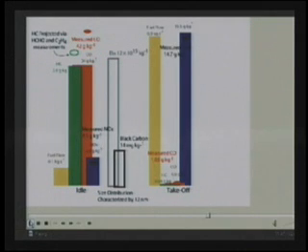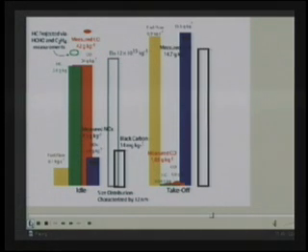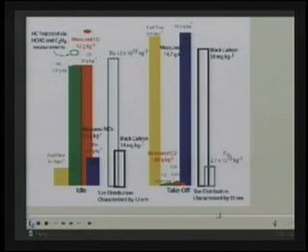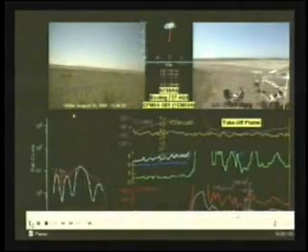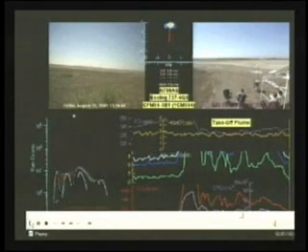the 85% number off the certification data, and that works out to be pretty close to what they were operating at, and that's what Southwest told us they were operating at, and that works out quite well. You notice the particle count is much lower, and the black carbon is much higher, and that shows up in the particle size distribution that we'll see just momentarily here. Okay, so yeah, the particle size distribution was peaked at 55 nanometers.